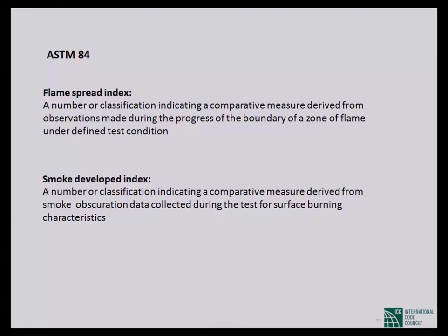Now I would like to talk a little bit about ASTM E84. Actually, ASTM E84 gives two things. One is the flame spread index, which is a number or classification indicating a comparative measurement. It's a comparative measurement, comparing with a standard material, red oak. How does the red oak behave? All the elements will be compared with this red oak, and it will give you a relative number. It can be in percent or it can be in time.